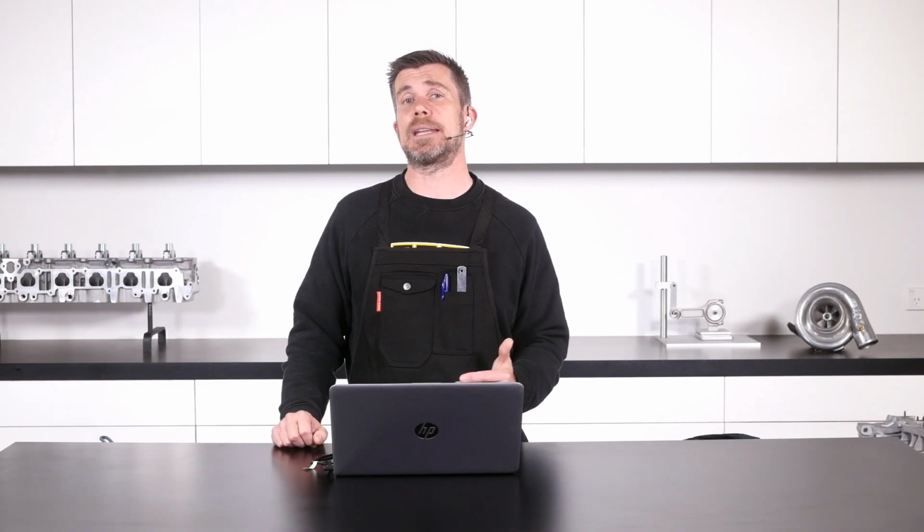So you just need a logger or an ECU that can bring that input in. Now obviously we've looked at the aspect there of just monitoring what your turbocharger is doing, basically getting some indication on your turbo sizing, whether you're on point there, and that's useful to a point. The other aspect though, as I've touched on, is we can use this as a load input to our ECU.